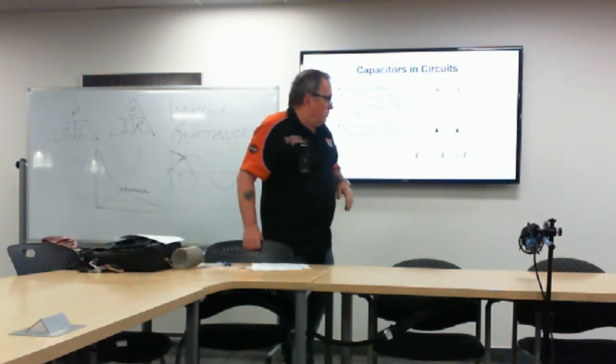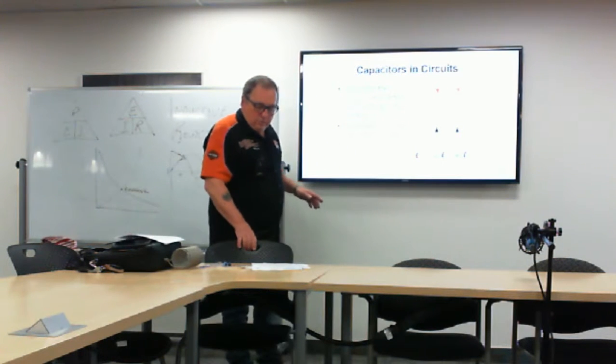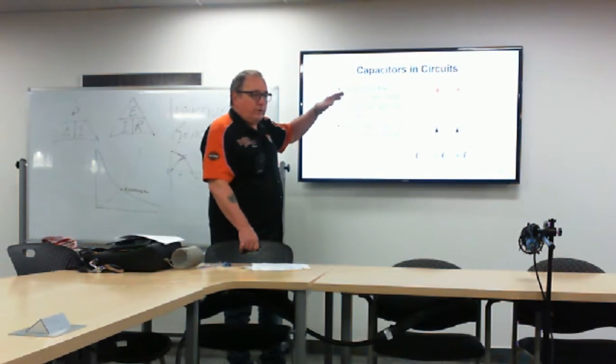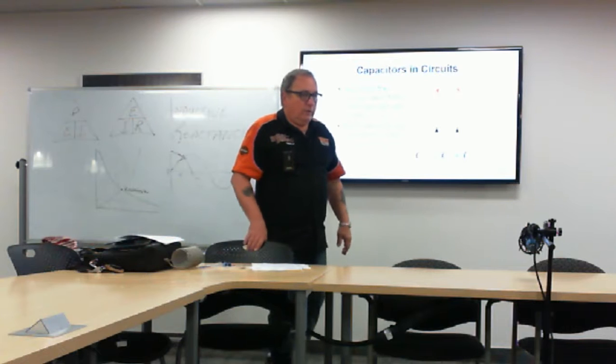If you know the frequency you want, and you know the inductance, you can algebraically solve for the capacitance that you need. Yes, to design your circuit. The frequency is 1 over 2 pi times the square root of L times C, henries times farads.